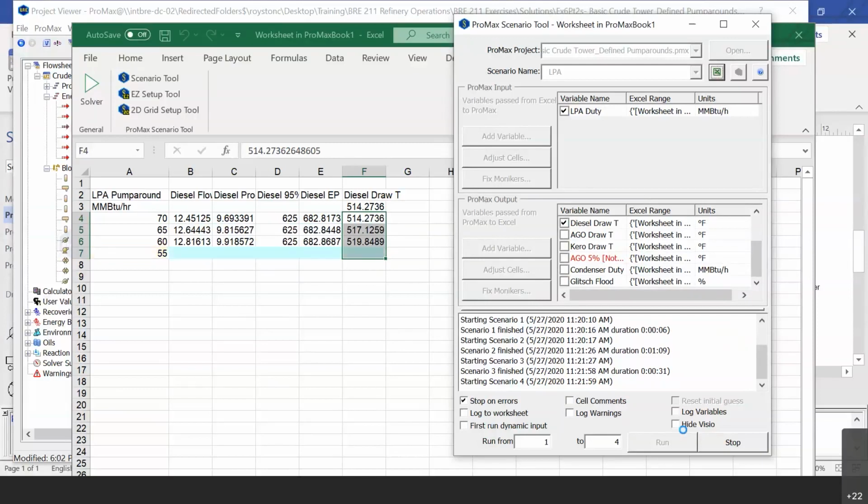Existing. So I think having a good match initially is important. You're going to determine what your efficiencies are based on your column performance. So the way I would do that is to take a column model and attempt to match it. If you have different crude rates in different draws, try to match them at different operating conditions, find a nice match there in terms of stages, and then certainly utilize an additional set as a test to see how well the match is.